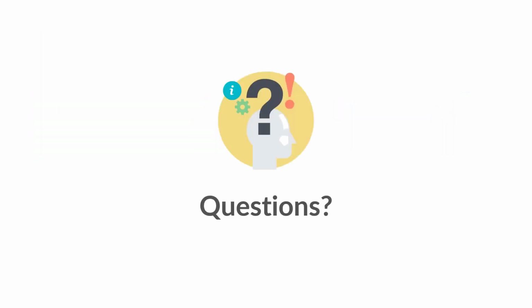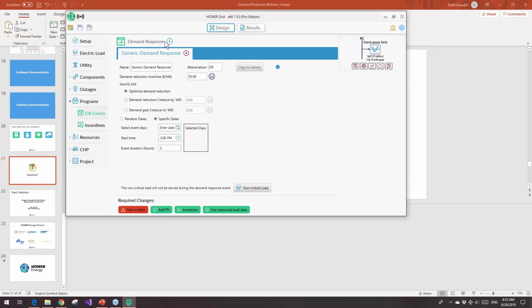And now I think we will get to the questions. I know that we've had a ton of questions coming in that Leah's been answering. So let's see. One question we had was, can you enter specific dates for demand response events instead of letting HOMER choose the dates? There's two different ways within demand response in HOMER Grid to specify the dates. You can either do the random dates or you can choose specific dates. So the answer is yes, and the toggle buttons are right in the middle of the page.